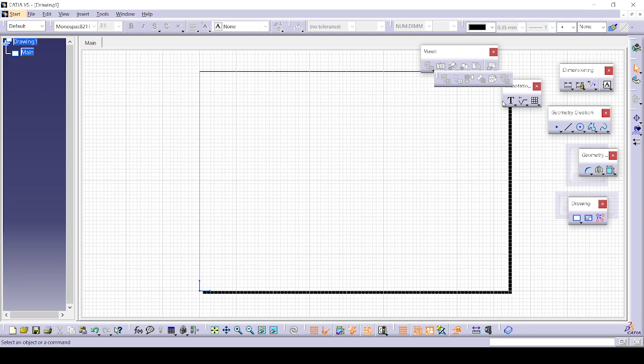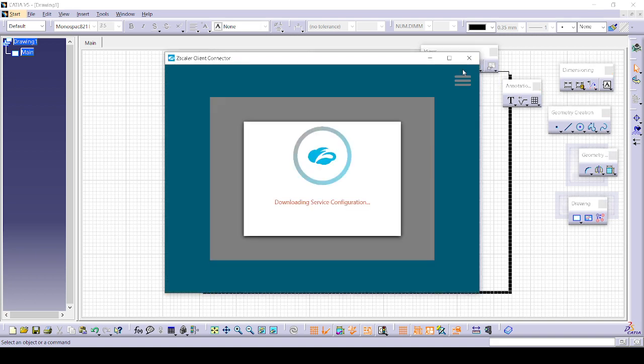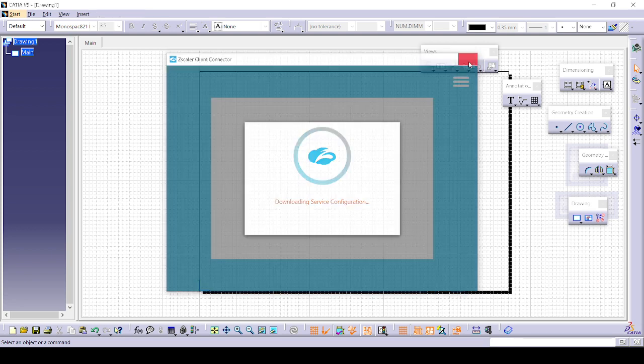Without 3D these views won't be activated. After that you will get different types of sectioning: offset section view, aligned section view, offset section cut, aligned section cut. These are also not activated because the primary view is not available in the sheet.